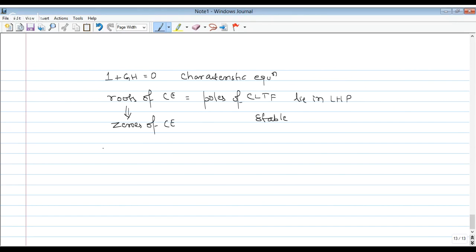What you can do is, for convolution in discrete time, sum of x of k into h of n minus k. So x of k is basically 1 from 0 to 4. After that it is 0. So k goes from 0 to 4, x will be 1. h of n minus k will be alpha to the power n minus k.